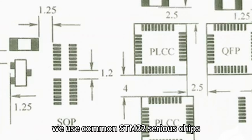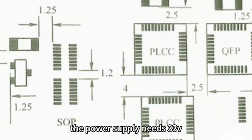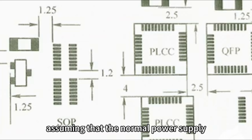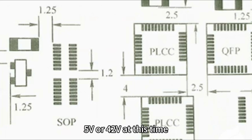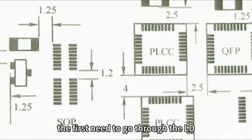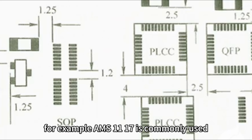We use the common STM32 series chips. The power supply needs 3V. Assuming that the normal power supply circuit power input terminal is 7.2V or 5V or 12V. At this time, it first needs to go through the LDO linear voltage regulator input terminal. For example, AMS1117 is commonly used.